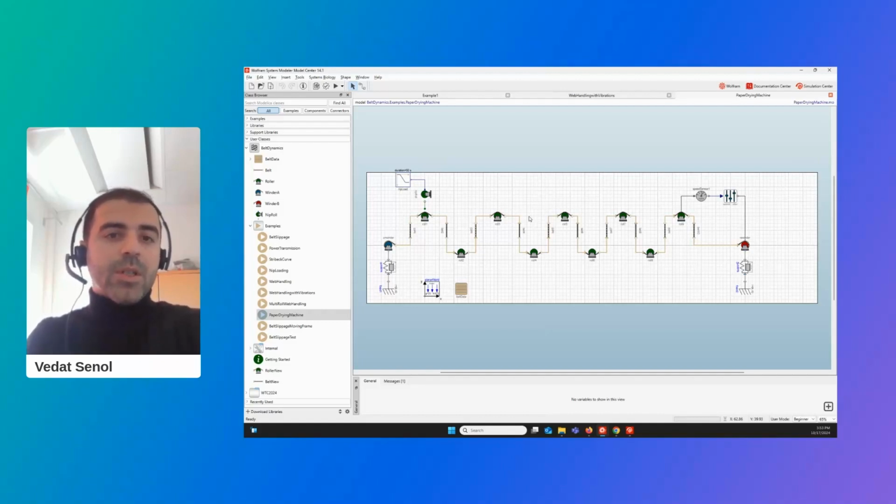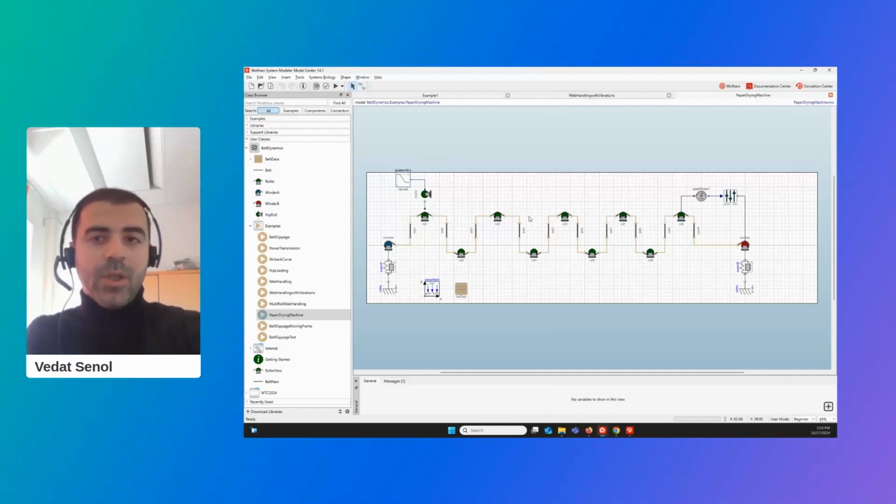So what we do in such scenarios, we create those systems with heated rolls, and depending on the heat transfer we can get out of those rolls, we specify a certain velocity, and that machinery should run at that speed so that we can reach our estimated or desired water content. And also we need to be really careful about the tension management so that the belt won't get ripped apart.